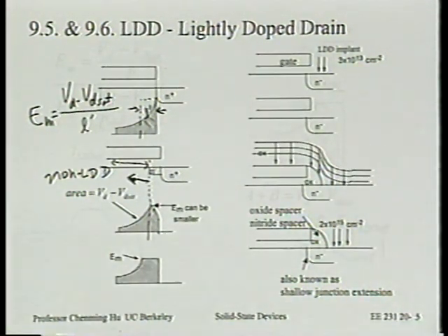So the problem usually is that power supply was given, and you're asked to design a transistor that can be shrunk to the smallest possible transistor gate length and still meet the reliability. So that's another easy way out of why we cannot simply drop the voltage. But the real reason is that actually if you go through that exercise, dropping the voltage gives you less performance than keeping the LDD using higher voltage. That's what it is, all right?